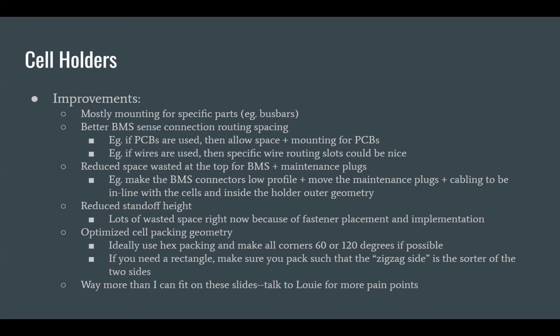And then let's see, BMS sense connections. Basically, like I mentioned earlier, the original plan for our BMS sensing connections was this uber sketchy thing: run a wire, solder the wire to a piece of nickel that we would then spot weld to the bar. Then we figured we'd find a better design if we needed to. Then we realized we need to have fuses on those wires. So now we're going to take a fuse, conductive epoxy the fuse to the bus bar, and then solder a wire to the fuse.